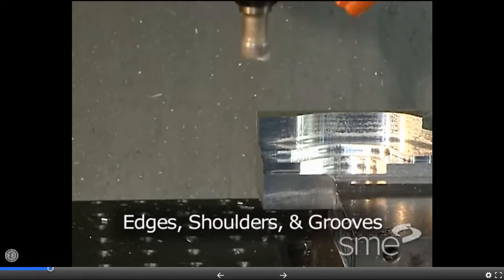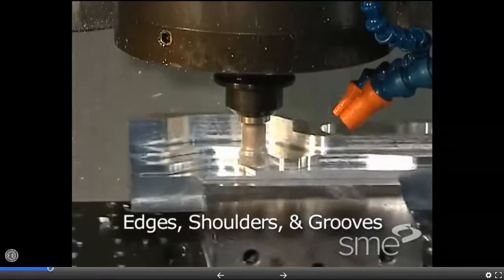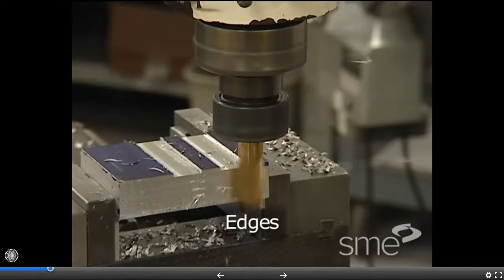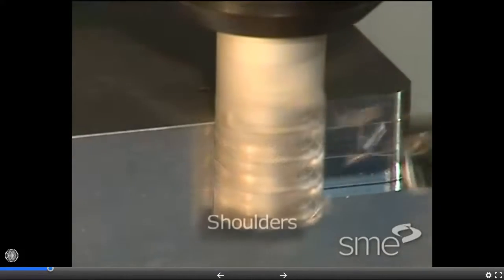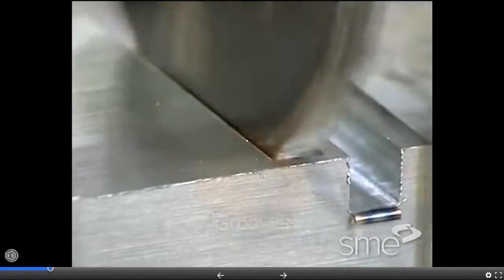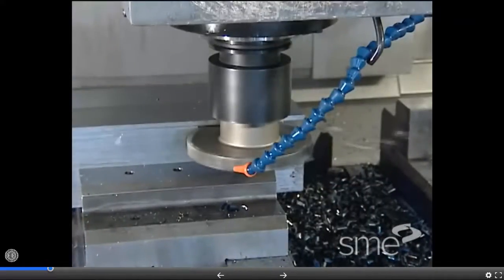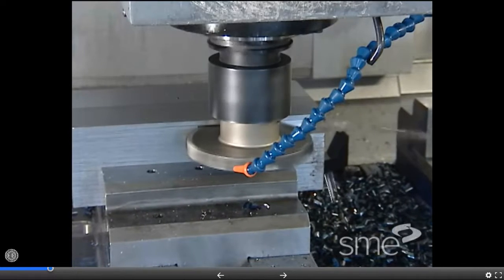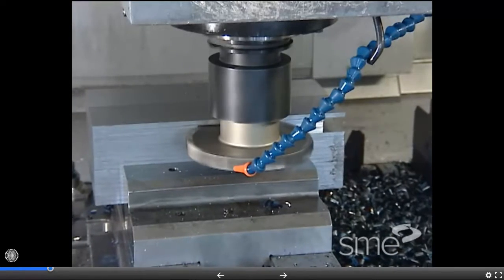Milling edges, shoulders, and grooves may use a combination of end, peripheral, and/or face milling operations. Creating edges or edging may involve the milling of one or two surfaces. Shoulders typically have two surfaces, and grooves usually have three surfaces. Grooves may be closed at one end or open at both ends, and they may be cut on internal and external flat surfaces as well as on round surfaces.